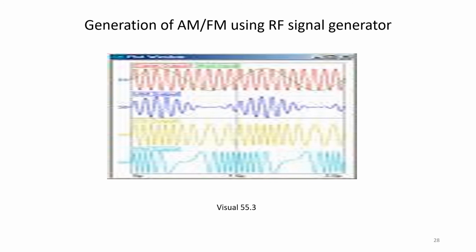An RF oscillator can also generate various RF voltages required for alignment and servicing of radio equipment. You can use an RF oscillator for measurement of gain of each stage at RF frequency. It can be used to determine the distortion characteristics of an amplifier. So these are the various applications of an RF signal generator. Thank you.